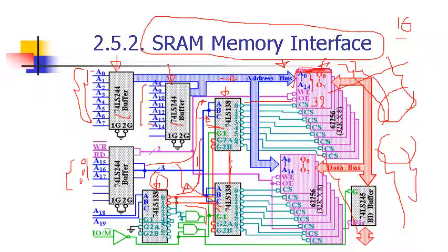Good. Okay, so you can follow the connection of this system easily. For example, A18, A19 are used to select the upper or the lower decoder. You may assign 00 for this line to be low, which goes and activates the upper decoder, and 10 makes this line low, which goes and activates the lower decoder.